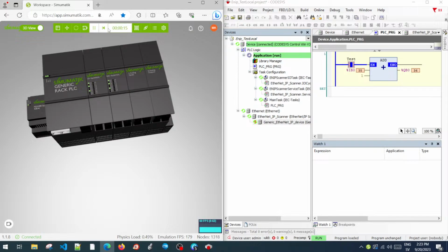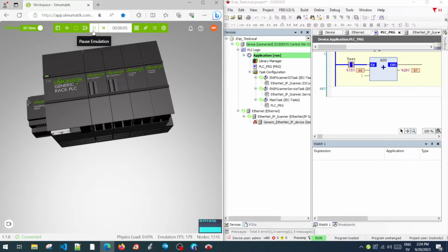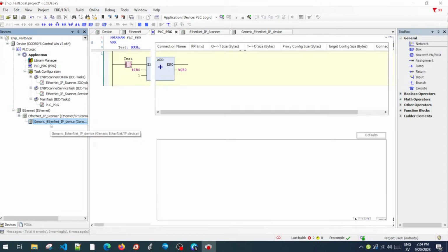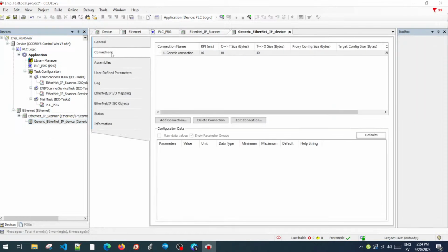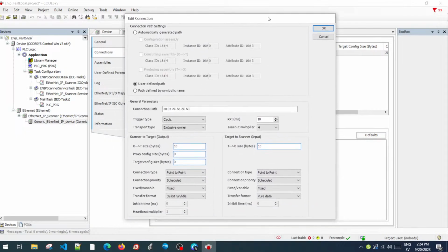Okay, so sometimes it takes some seconds until it reconnects, even if we click play, but it has nothing to do with Simumatik itself. As I say, when we click play, the driver just starts and waits until the PLC decides to try to establish a connection and send telegrams. And you see, it's kind of random. Actually, maybe it's not that random, because I think here in Codesys we have an option to define how often we want to reconnect, if I remember. Somewhere here, I think, timeout.